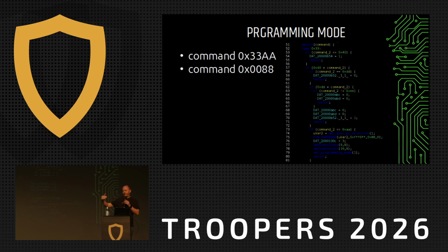There's another place in the firmware where the other command is 0088, does the same thing. So basically, looking at the reverse engineering of the firmware, what we can see is that anyone on the bus sending in any of these 2 commands can immediately put any device that this is addressed to into programming mode without any authorization or anything. And then you can start reconfiguring it.